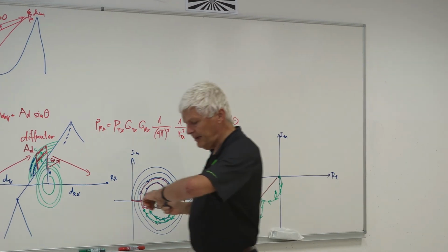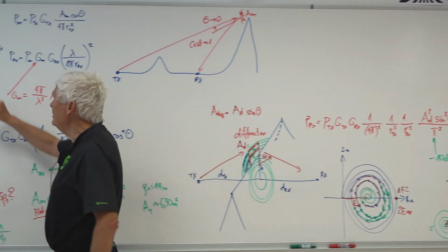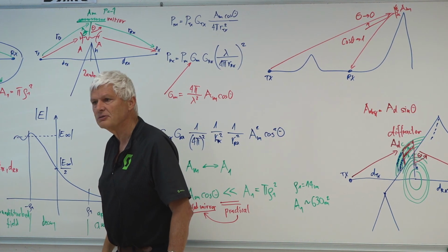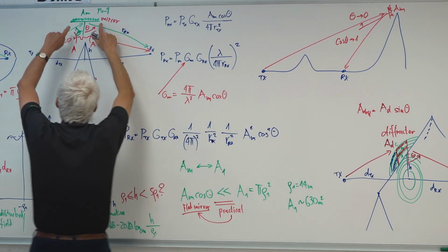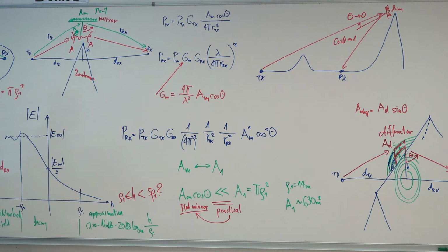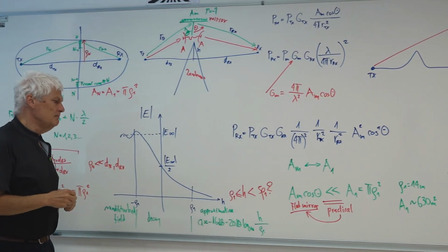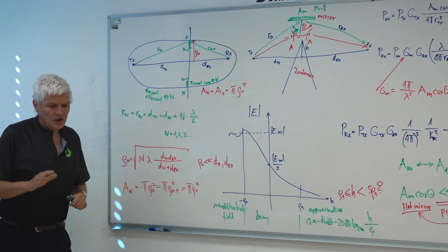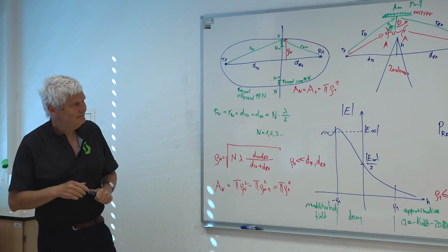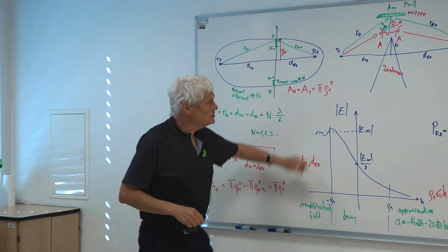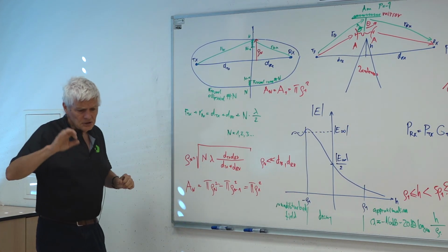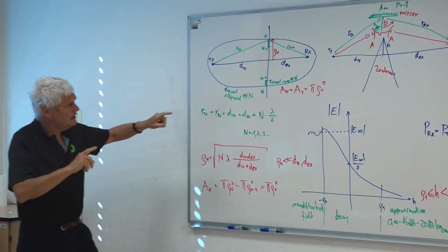Just one detail about the mirror. You install your mirror on the mountaintop and then it works? No, it doesn't work. You have to point this mirror very accurately to hit your receiver on the other side. And this pointing of the mirror, considering typical links in our countryside here in Slovenia, you have adjustment screws on the mirror and you have to adjust the nuts of these screws and slowly adjust the mirror trying to hit the receiver.